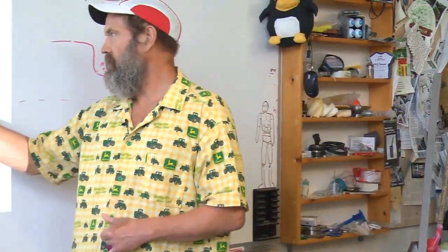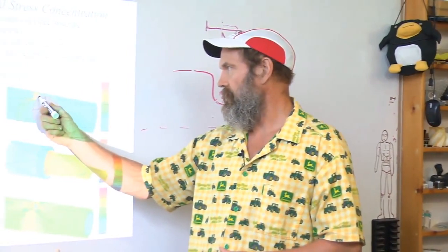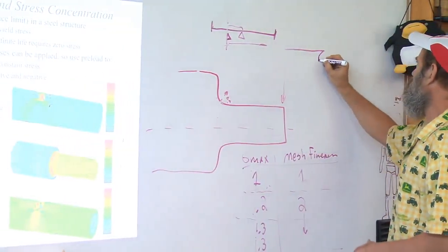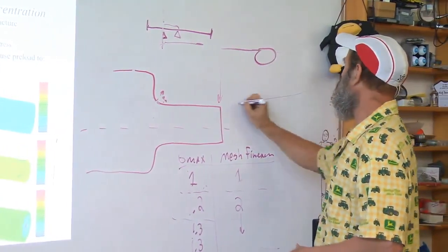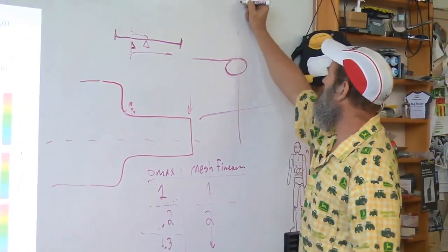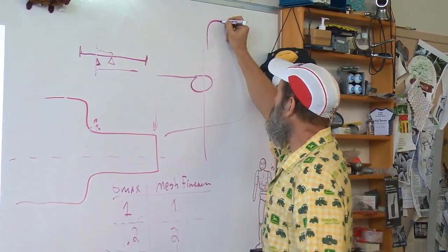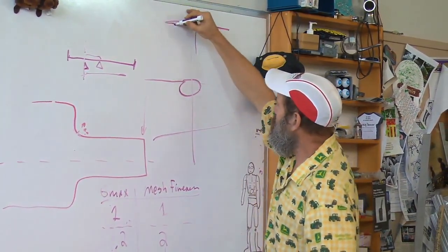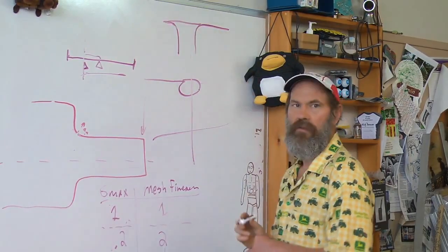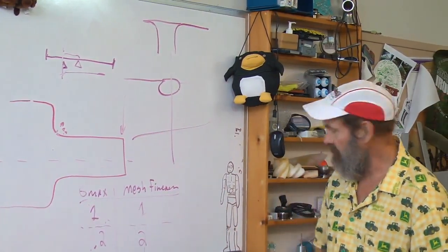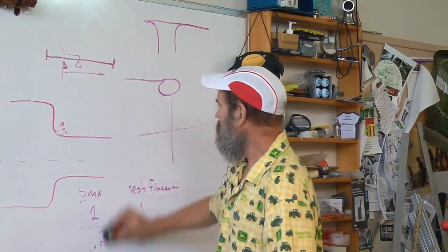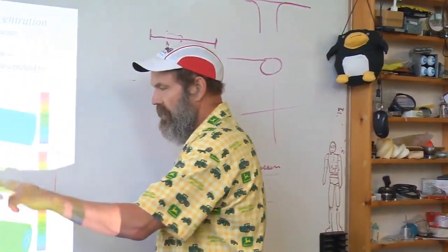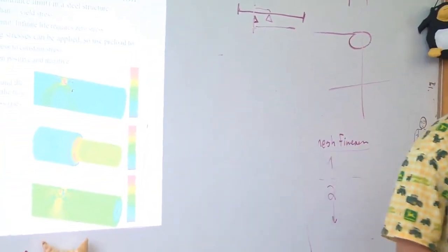And once you do that level of fineness, and now I have, for example, this hole in this shaft, now you can start playing the game of, here's the hole in the shaft. Should this hole, if I do a cross-section, have a nice gentle fillet on itself? Will that help lower the stress? Keyways on shafts are notorious for causing high stress concentrations. You know, keyways on shafts or holes in shafts.